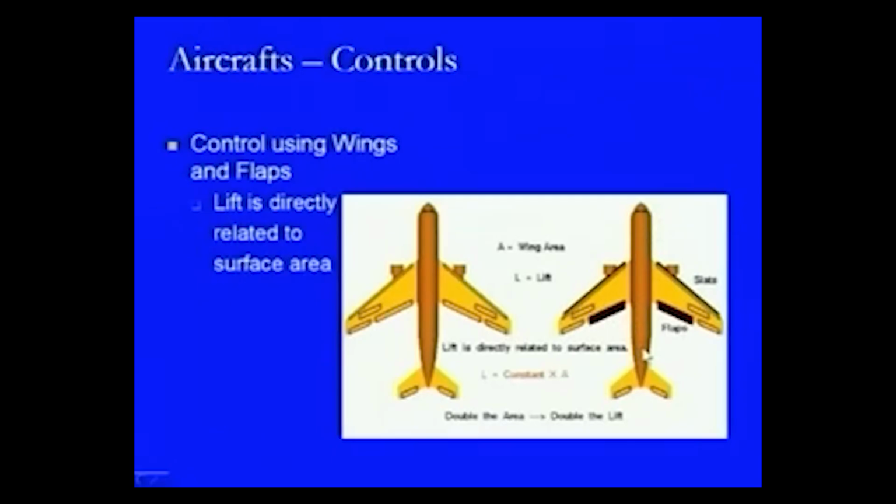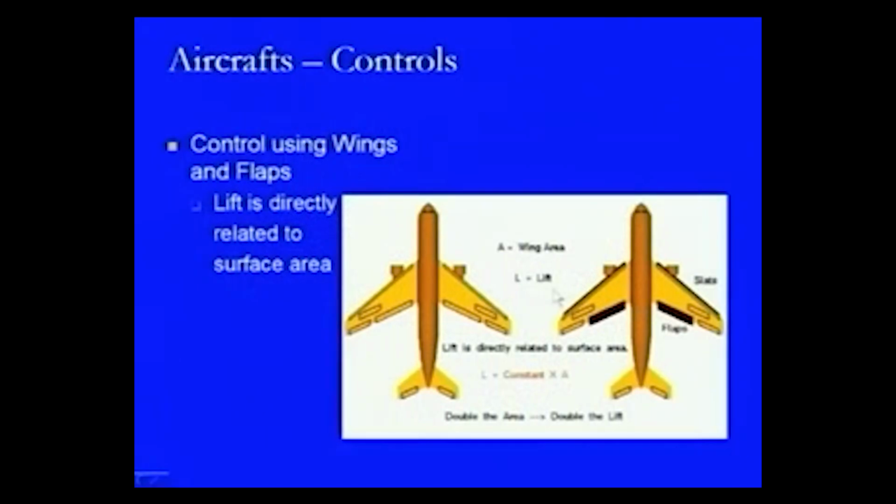So, what we do is that at the time of landing, the pilot is not using the brakes so as to reduce the speed of the aircraft from something like 300 kilometers per hour to 90 kilometers per hour at the time when it is going to take a turn from the runway and coming to the taxiways. So, the speed which is being reduced in this portion from 300 to something like 100 kilometers per hour is being done with the help of these flaps only, and the drag force which is generated by using the flaps. Then only after that the pilot starts putting some brakes as and when they are required.